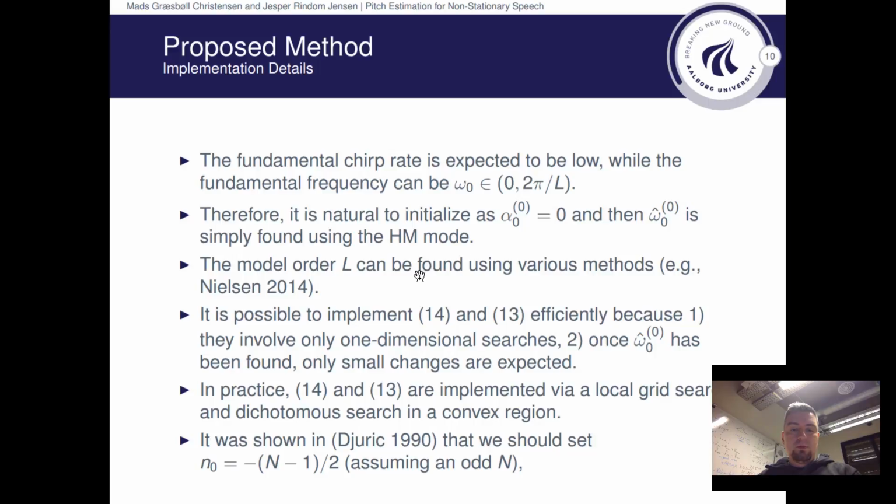And well, also a comment about the model order L, because I've been including that in all the equations here, but I didn't really talk about it. If you look at speech and audio signals, you actually need to find this model order L typically on a segment-to-segment basis, and that you can do in different ways, including the AIC, MDL and BIC criteria and so forth, which is completely consistent with what's going on here.